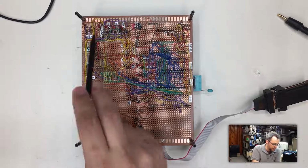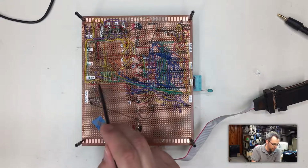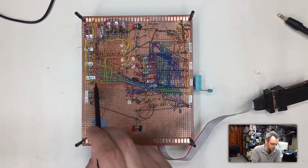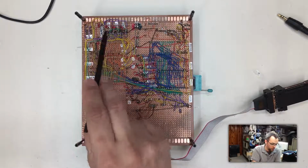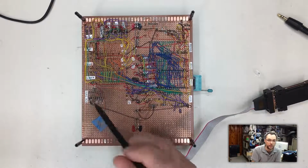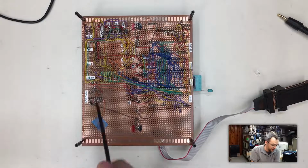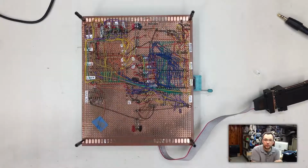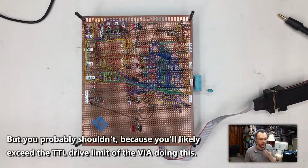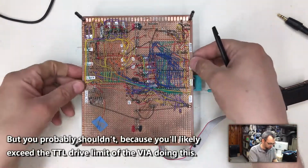And then you select the chips by just turning these individual pins on at the output, and that will turn those chips on. Because these pins can be turned on simultaneously, you can, in theory, send the same command to all 3 potentiometer chips simultaneously if you wanted to, but whatever.